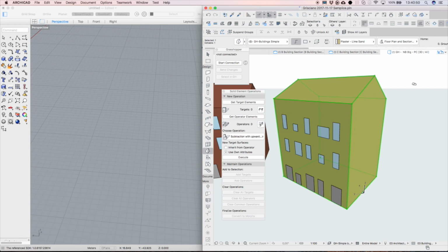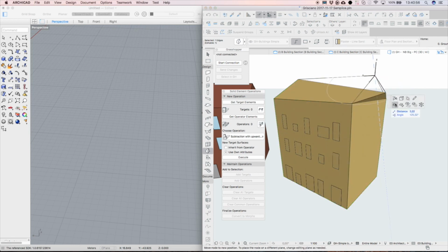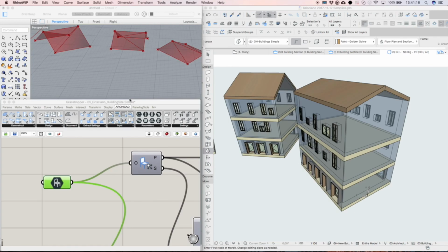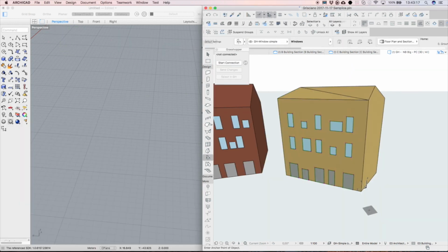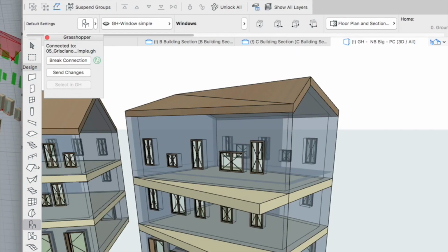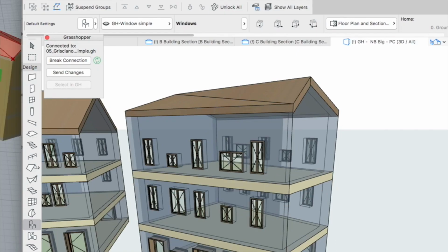We'll display the conceptual Morph shape in the 3D view of ARCHICAD once again. Let's select the Morph shape and change the height of the ridgeline of the roof. The geometry and shape of the final roof object will be updated based on the modified Morph shape. In this example, we will change the geometry of the initial shape of the Morph element. Please note that the wall and slab element shapes and positions will be updated instantly to reflect all changes made to the conceptual Morph shape.